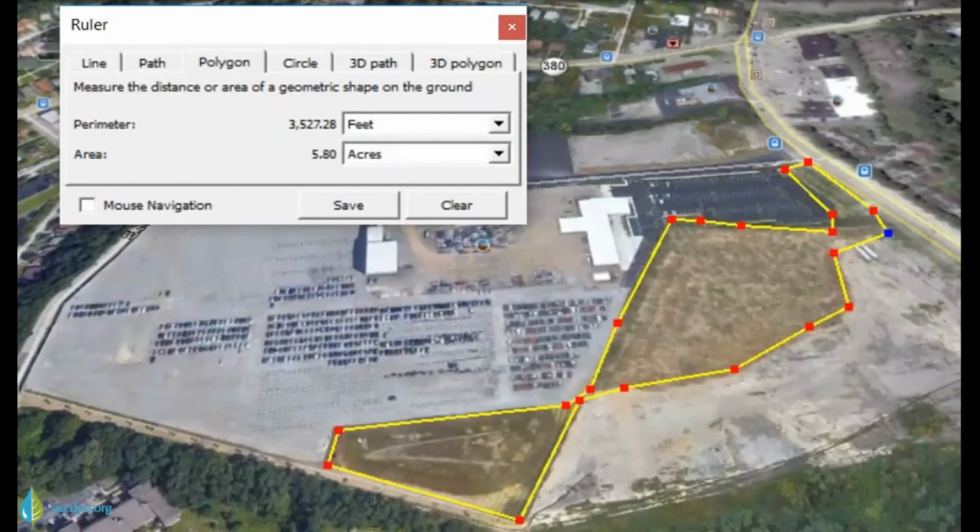The redevelopment resulted in substantially more green space on the property, including a nearly 2-acre infiltration basin and just over 3.5 acres of a restored meadow where all of the pavement was torn out, the subground was scarified, topsoil was brought in, and it's a 3.5 acre meadow and grass, up to your waist type of restoration.